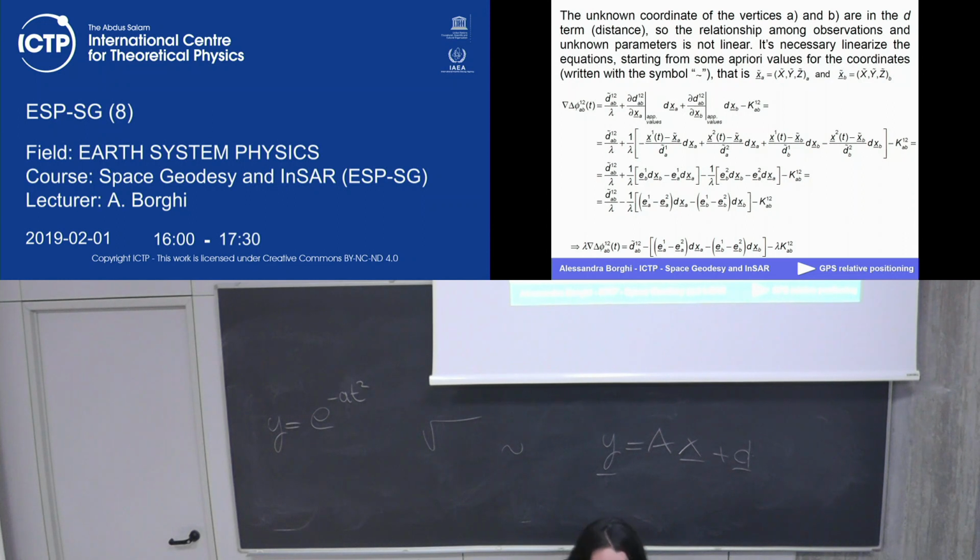It depends. I told you that the precision in the planimetric position is higher than the precision in the height component. Why? Because we have seen that we have problems with a lot of things that are related to the height, for instance, the troposphere and so on. The planimetric position is more constrained than the height, because it's really related to the number of cycles.